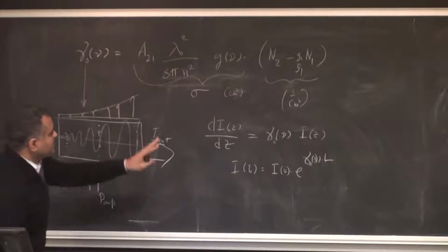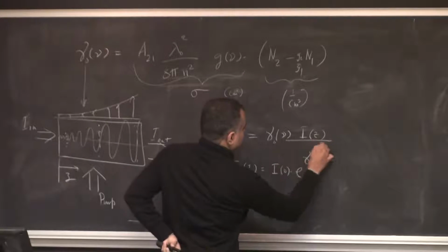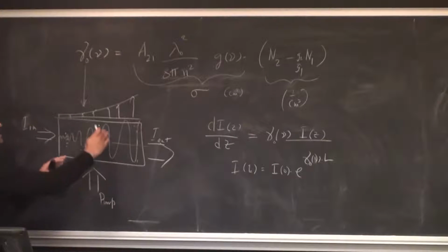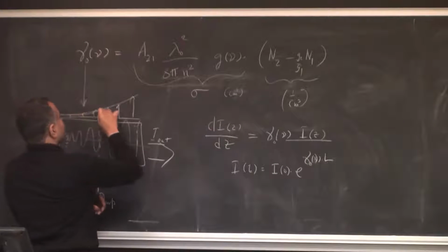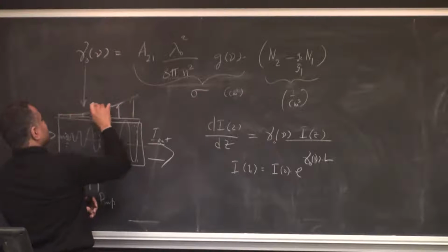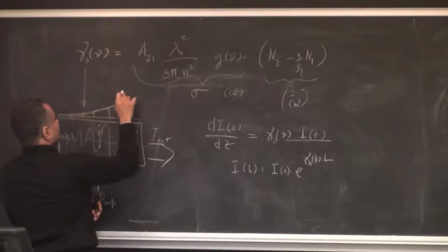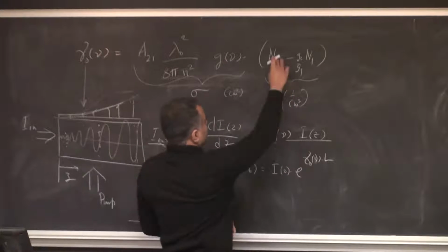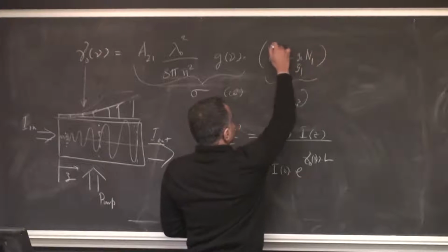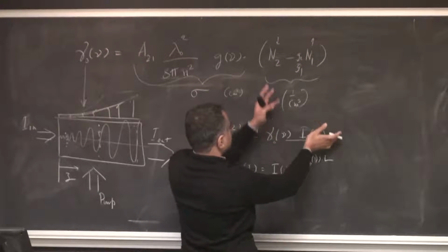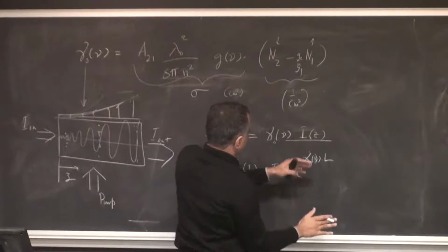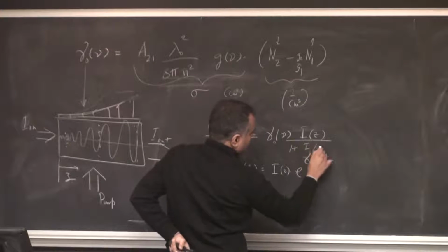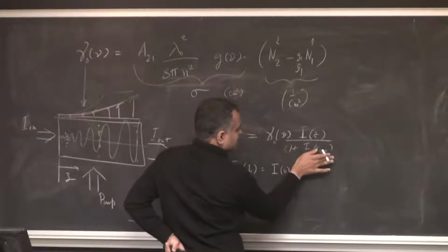The other detail I don't want to get into right now is that no exponential goes on forever. If you reach very high intensity, the gain will saturate, because every time you create inversion, you are losing this and gaining this. So the gain spectrum collapses slowly. That is taken into account by the large signal model, which adds this little term here.